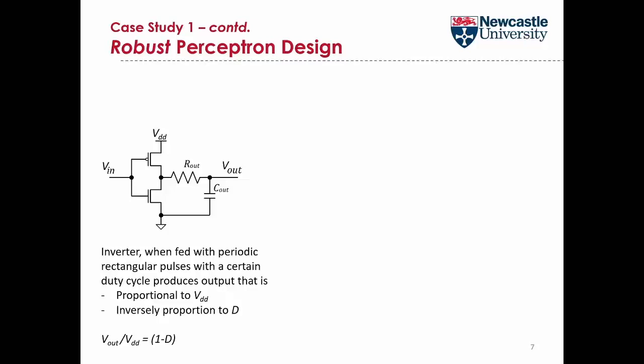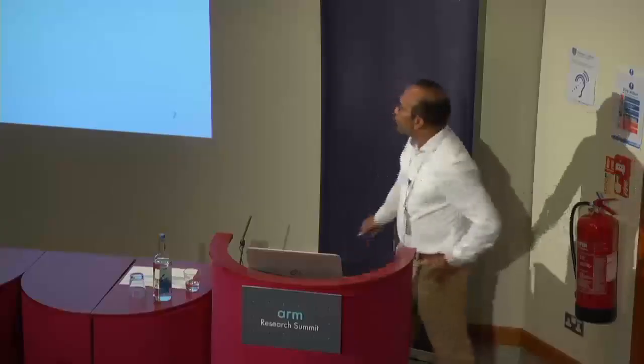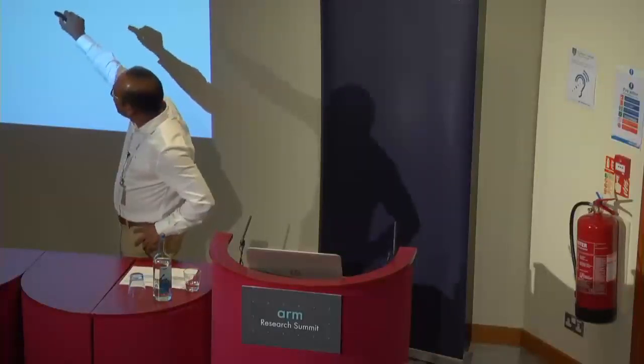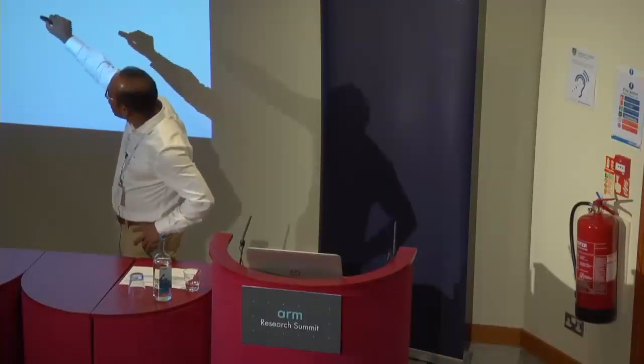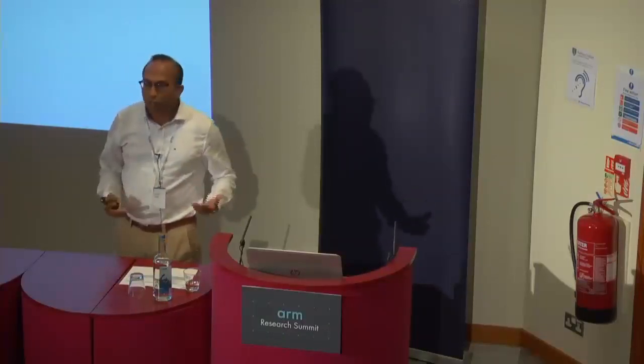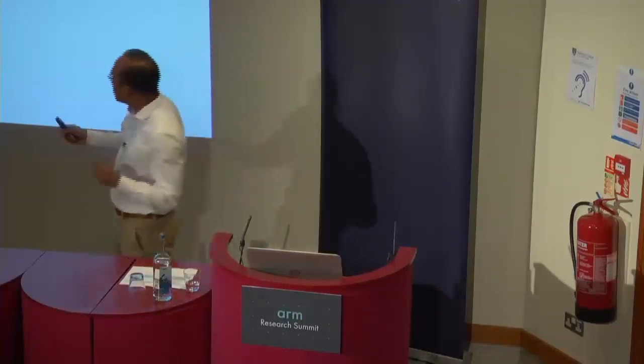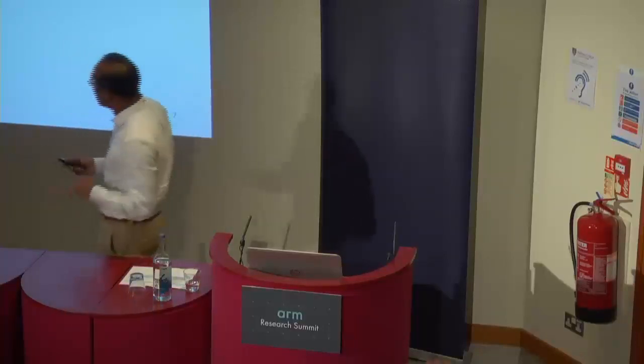The only relationship is that the output will be proportional to the VDD, and also proportional to the duty cycle, and completely agnostic of what you have put in at the input side. This is a fantastic property, which basically means that if you change the VDD and also the frequency at the input, the output is still going to be defined by a duty cycle. That's really good, because that gives you the stretchability across different power domains, because voltage and frequency are pretty much what define the power in the circuits.